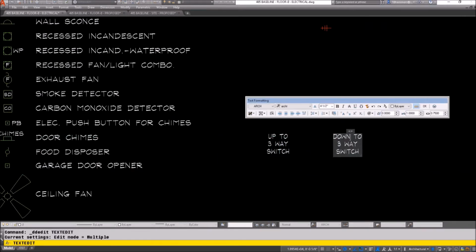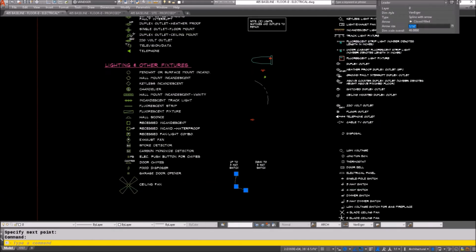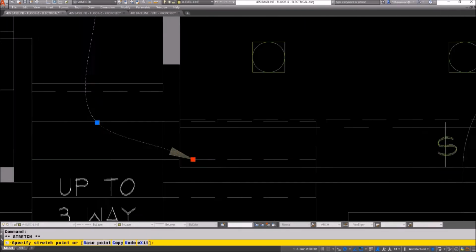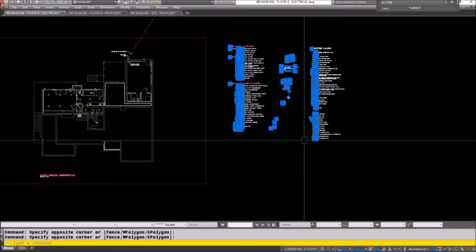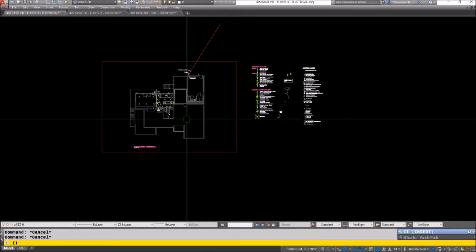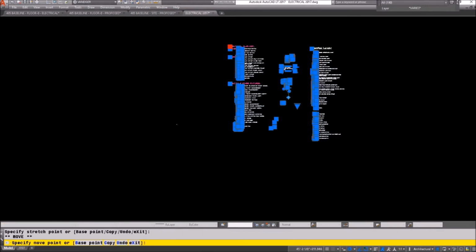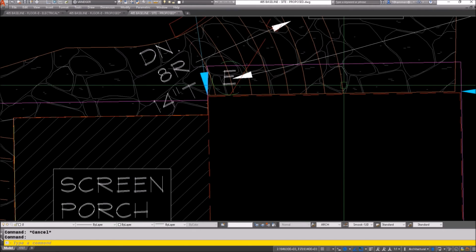Oh, this is something I wanted to add to my template. I always have this thing where I'm running a wire up or downstairs into the next view, and you've got to tell them where it goes. So I just made this little note here and kind of made it go hot rod, the performance. Then I W-blocked that out so it would be in there next time. And then I realized, oh crap, I didn't use the origin properly. So I had to go to the actual block and reset the origin so that it was at 0,0 instead of somewhere out in space.